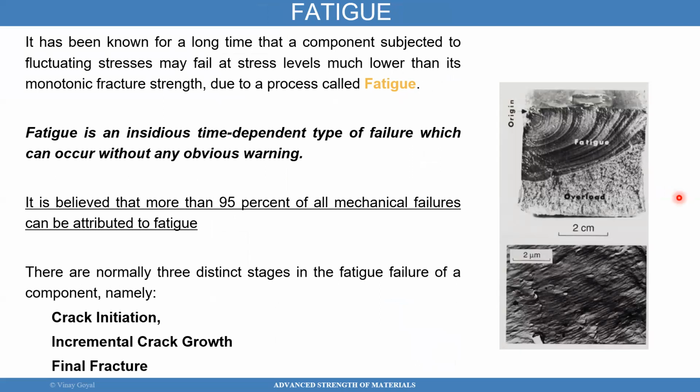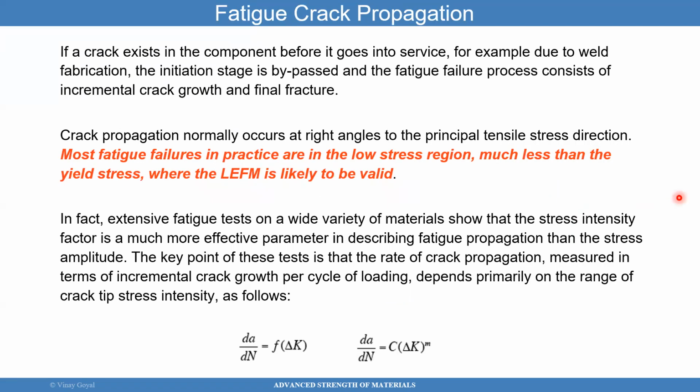Crack initiation and failure due to fatigue of that crack that initiated accounts for a large number of mechanical failures attributed to fatigue. We're going to assume that linear elastic fracture mechanics is valid, and we're going to use the Paris law relationship here at the bottom.